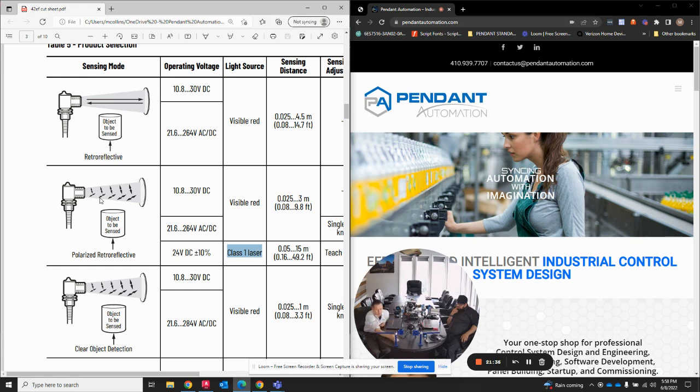And so one of the nice things about this is if they mounted the photo eye directly across from the reflector and you actually needed to put some angle of skew in there, you can do that just with an Allen key. Like I said, they're super expensive, but in our experience, the fixed position mounting brackets, you have to get them perfectly right. You have to align them, and a lot of times the electricians do not pay attention to that. And then you're left holding the bag at the job site when you need to align a photo eye.